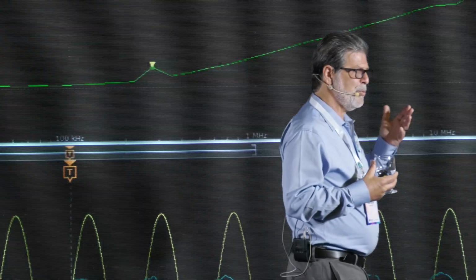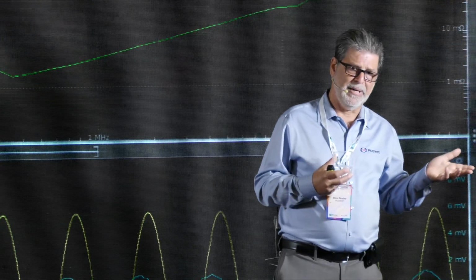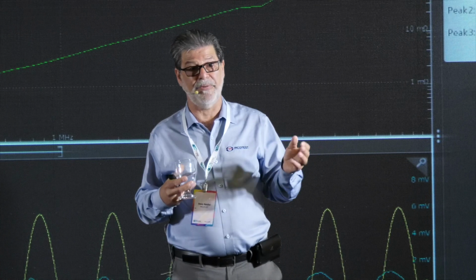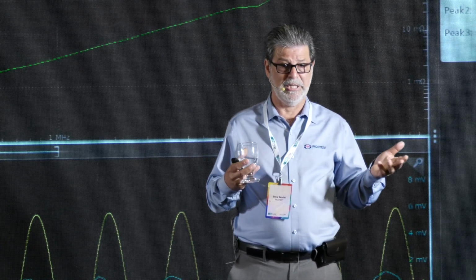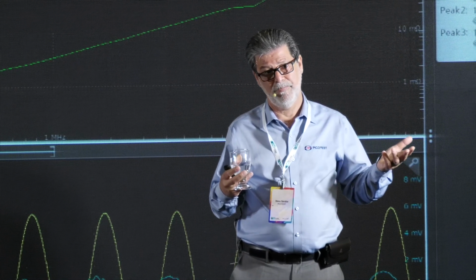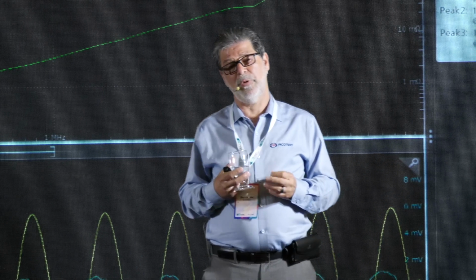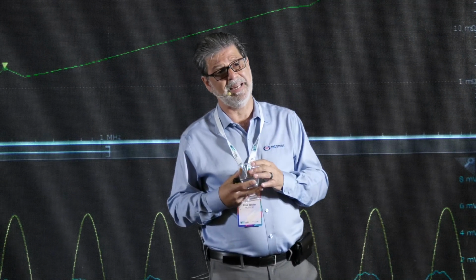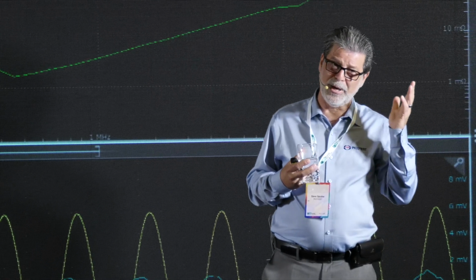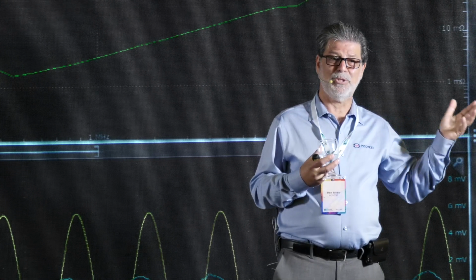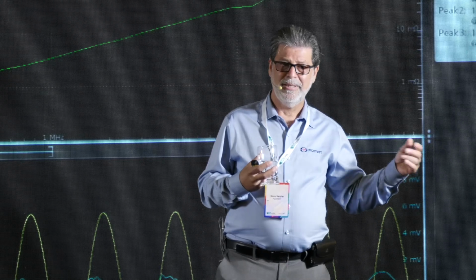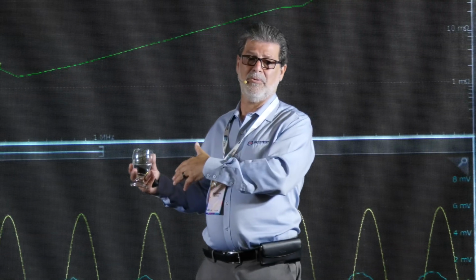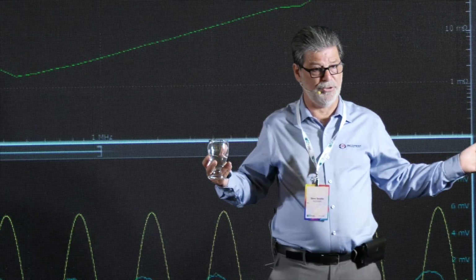On the other hand, pushing the switching frequency up, well, there's some benefits. One is that you can make higher bandwidth, the filter caps get smaller, lots of benefits, but the losses go up. In some cases, we really have to make trade-offs. In the case of Xilinx, I had to push the switching frequency up to get the switching inductor to be smaller, to make the caps small enough we could tolerate. It wasn't an ideal choice, it was a trade-off.